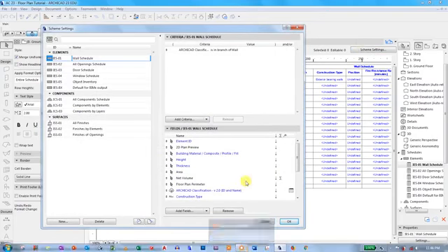Now based on the standard method of measurement for your country, you can be able to tell what type of information for the wall that you need for you to be able to come up with a cost for that. And for me, I should understand the type of material that I am using to build my wall. I need to know the wall height, and I already have the wall height here. I also need to know the thickness of that wall.